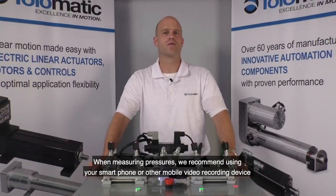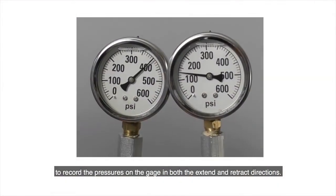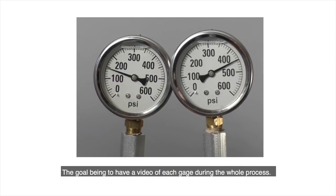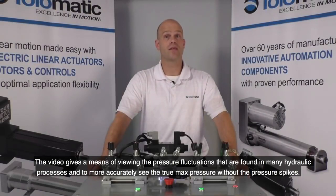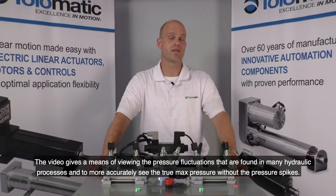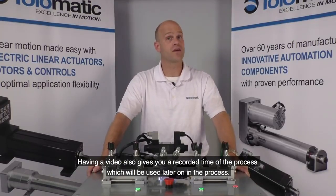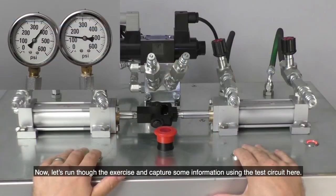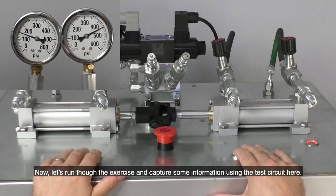When measuring these pressures, we recommend using a smartphone or other mobile device to record the pressures on the gauge in both the extend and retract directions. The goal is to have a video of each gauge during the whole process. The video gives a means of viewing the pressure fluctuations that are found in many hydraulic processes and to more accurately see the true maximum pressure without pressure spikes. Having a video also gives you a recorded time of the process, which will be used later on in the process.